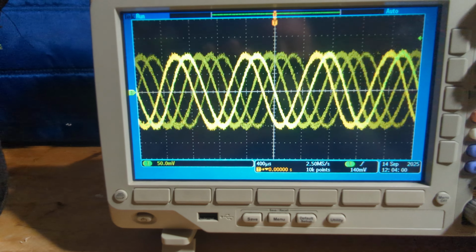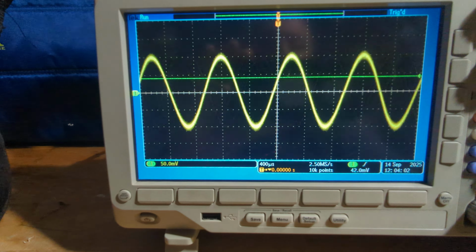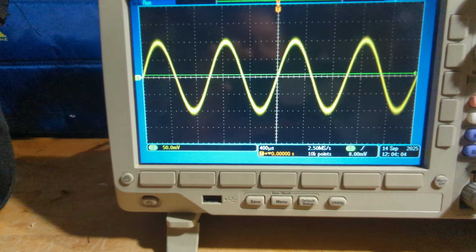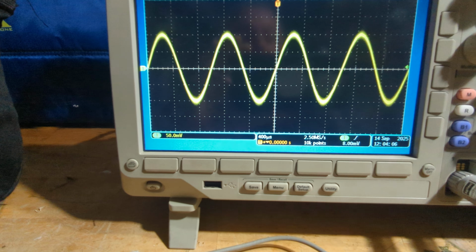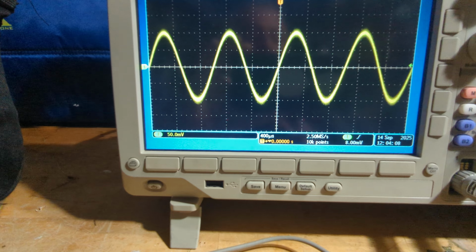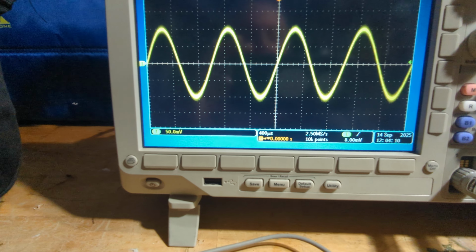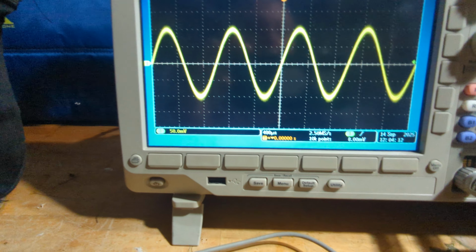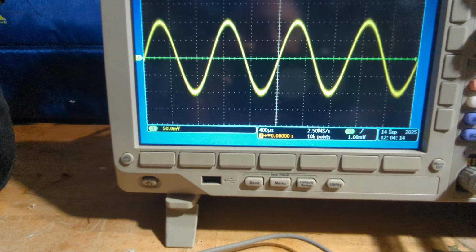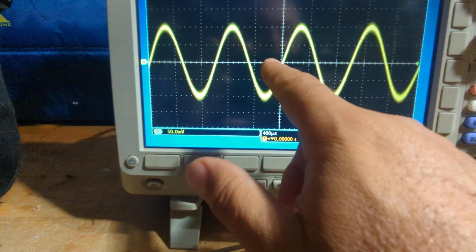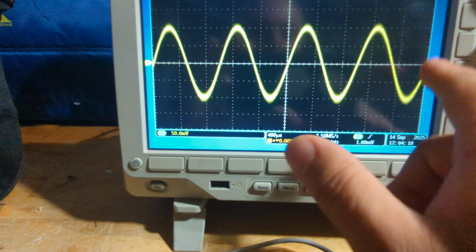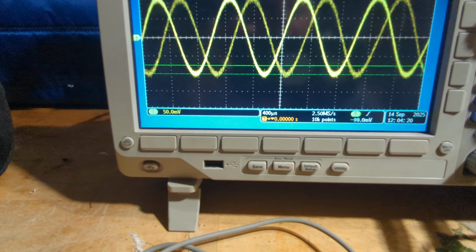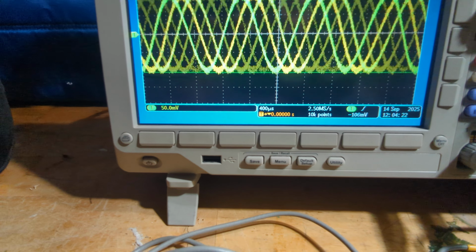And now it doesn't know where to begin and end. So the way it knows to write over the same waveframe with the same period of the window is wherever that trigger is, right? It says that's the beginning of the waveform. And so it's looking for that point, right?